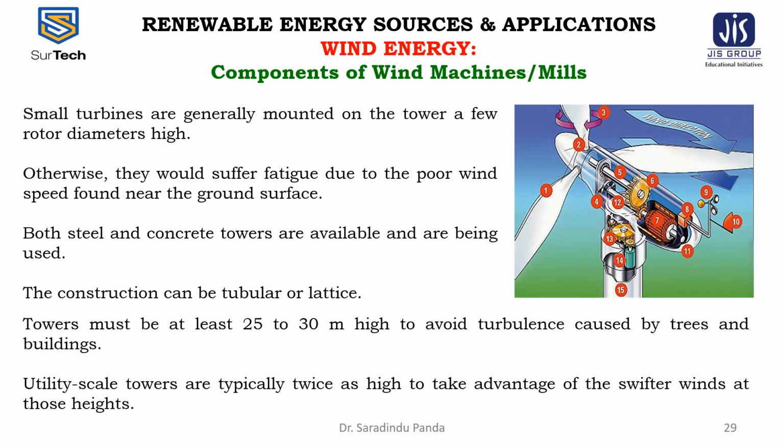This requires careful avoidance of all the resonance frequencies of the tower, the rotor, and the nacelle from the wind fluctuation frequencies. Sufficient margin must be maintained between the two sets of frequencies in all the vibrating modes.